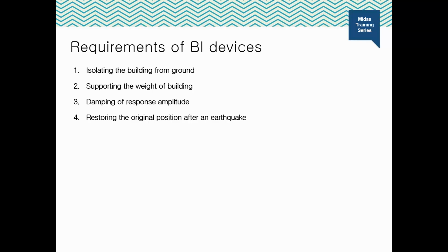Overall, due to base isolation, a lot of cost can be saved. The force experienced by the members in the structure is reduced drastically, hence saving the cost of the concrete and the rebar material. The vertical load is also reduced, hence saving the cost of the foundations. In this way, using the base isolation devices, we can have an economical design for the seismic structures.